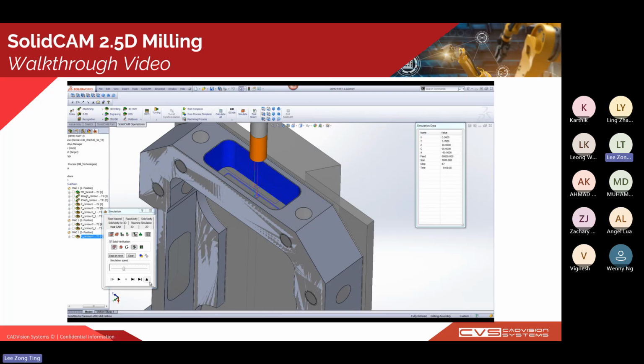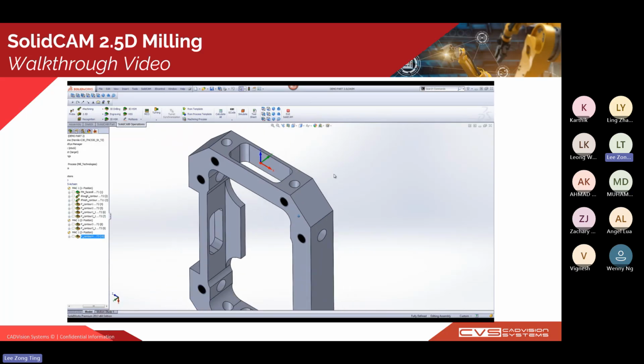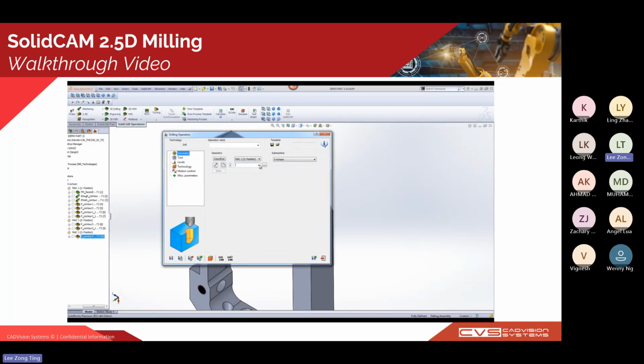But we don't know which point the end mill is going to enter, and we cannot sketch a point to specify the drill entrance point. So what we can do here is select the drilling operation, and you can see here in the geometry tab, we can directly choose the entry point of the end mill itself.